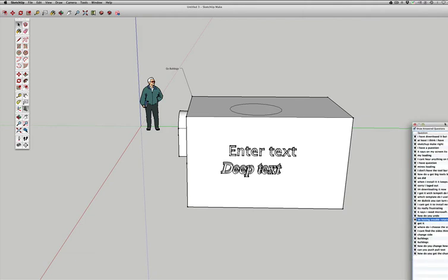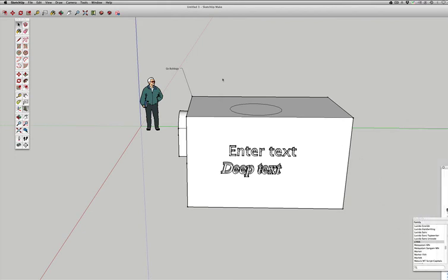How did you change the number of sides? Ryan, I just showed you, buddy. Right down here. Come here, I'll show you one more time, bud. I go to polygon right here, and I just type it in. Like when I go to click on it, right now it shows 18 sides because that's the last I had. Say it's circling around. I don't want to type down there. I just simply type right now 6. I do 6, and then I click on this. It's now got 6 sides. It's just going to ask me the radius, which I'll put in this case 400. I just do that just because.